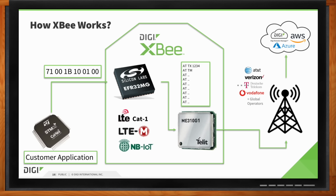So you can always be encapsulating your data and formatting it in a certain way when you're communicating with our XBee device. And then we can decode that and send maybe a long series of AT commands direct to the cellular module in order to establish that cellular connection or that TCP socket connection, transmit that data, and then close that connection back up. For you, it's just one simple command that you're used to sending in, but for us, it may be a series of different commands that allow you to do that securely and to make sure that data reliably makes it where it needs to go.